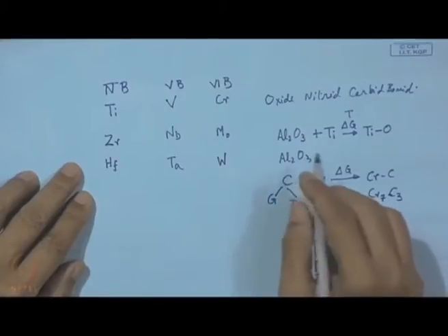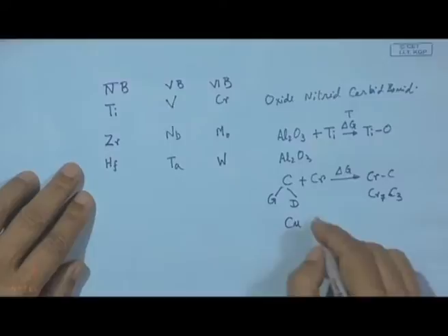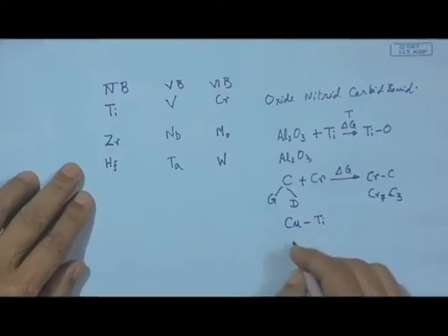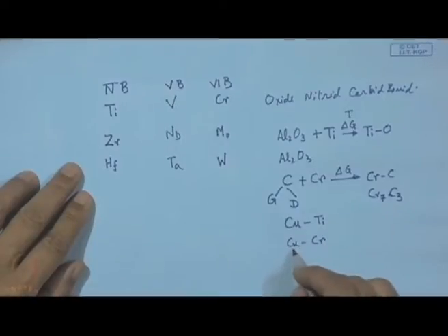So, if the basic material is copper, say for example, and we add chromium to the copper, we see whether this chromium carbide is formed so that the copper can wet this surface.